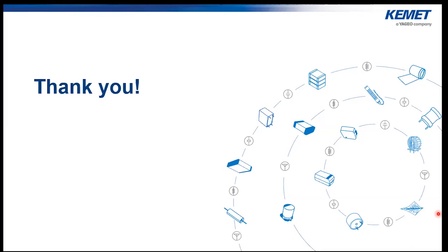You could also use film capacitors, electrolytic capacitors. But the key thing is that the tantalum capacitor is going to be used for frequencies lower than a megahertz. So I hope that answers the question.